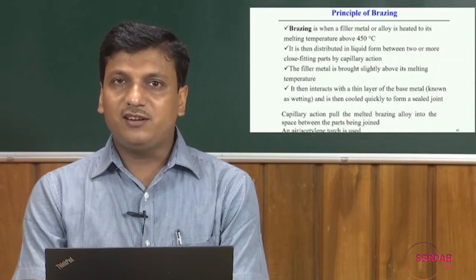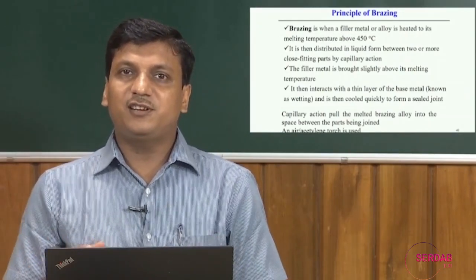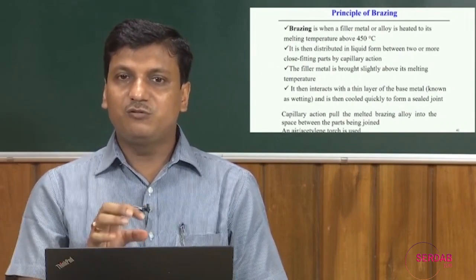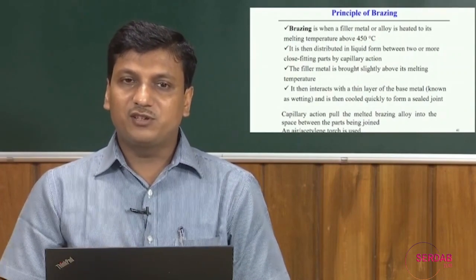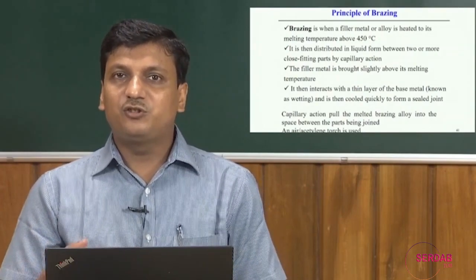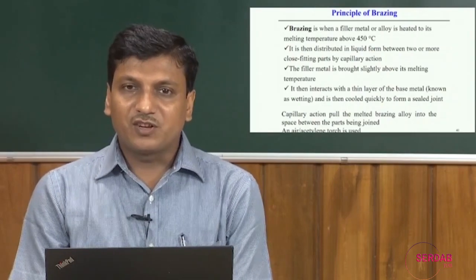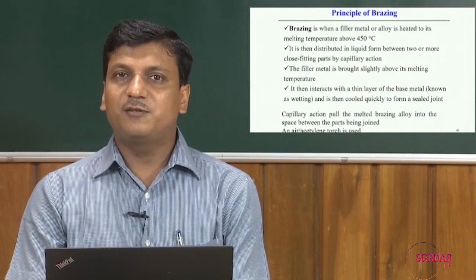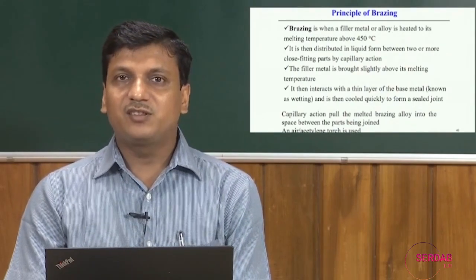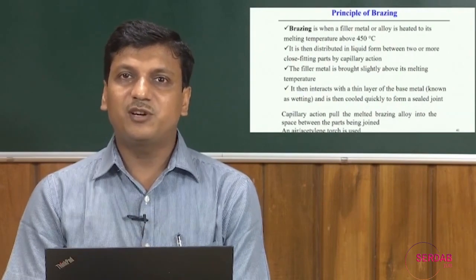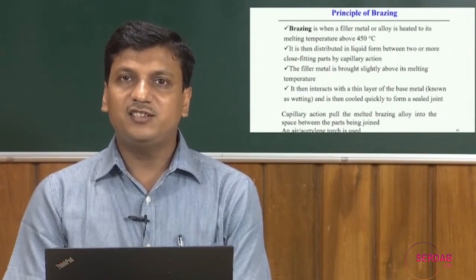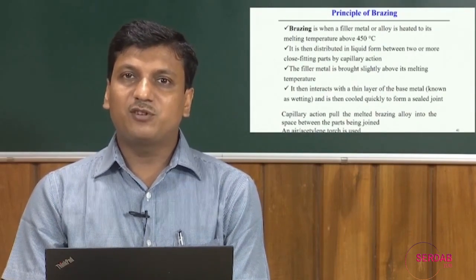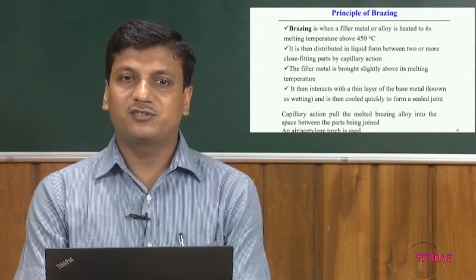Then, when it exactly fills the gap between the two solid metals, after some time it solidifies or cools down to the ambient temperature, and that finally creates the joint between the two base metals. Of course, the intuition is that in this case the liquid metal is simply wetting the solid metal. So, we cannot expect the very high strength of this joint like any other fusion welding processes or any other solid state welding processes.